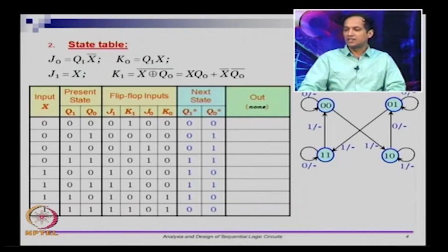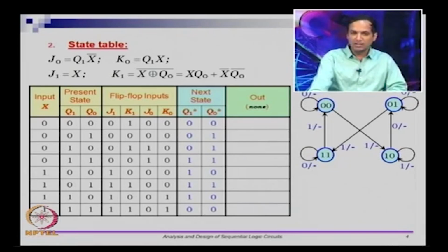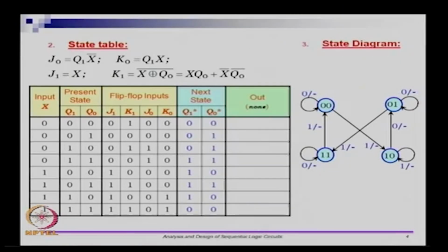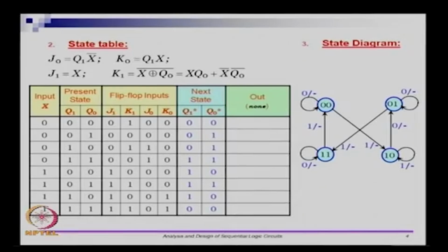This is the state machine that describes the circuit that is given earlier. So, this is a fairly straightforward and simple example. It was easy to get different equations and so on. In the real world, the state machines are not just 2 bits, it gets a lot more complicated, and if you have to analyze a circuit, you have to do this process of getting all the equations, finding out what the flip flops are, and based on the flip flops you have to derive the next state.